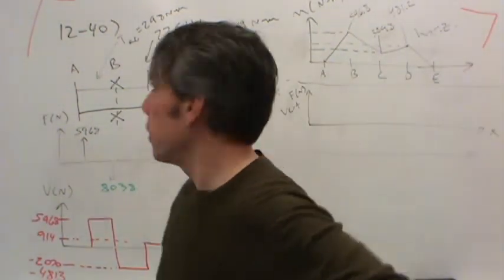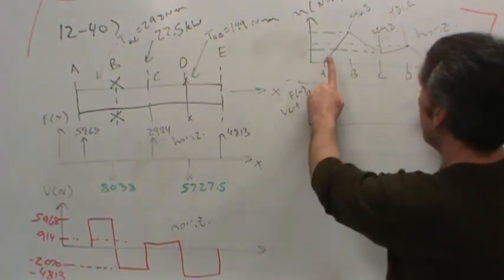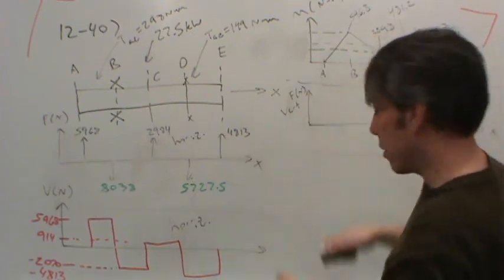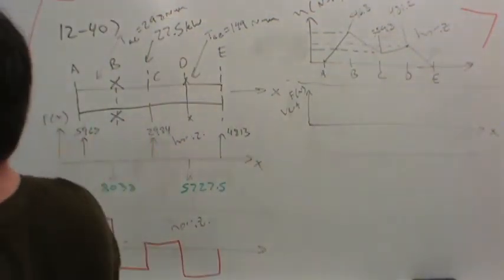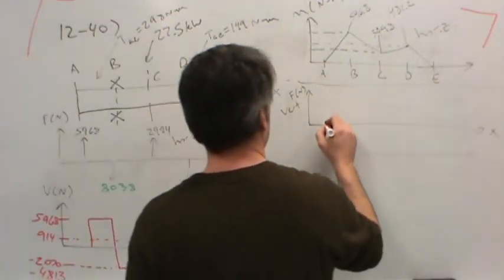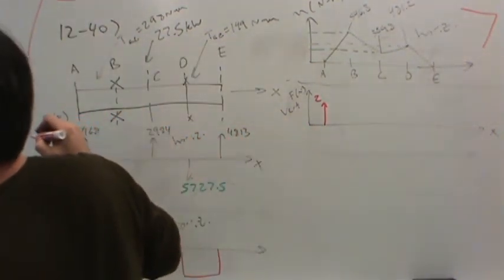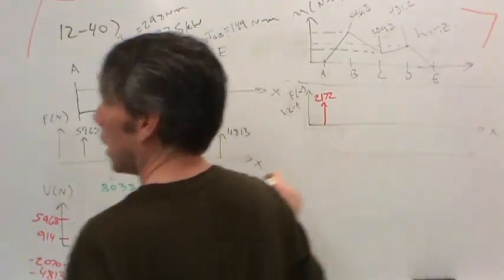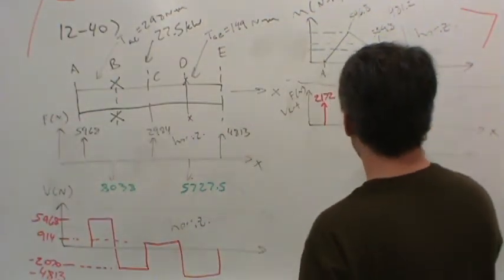Now if you remember, when I had the diagram up here, the radial loads were both up on A and E, but down on C, okay? So let's put those loads in. I'm trying to stay away from the black pen because it's running out of ink. But the radial loads were 2,172 or so at A. At C, the radial load was 1,086, but it was in the opposite direction.